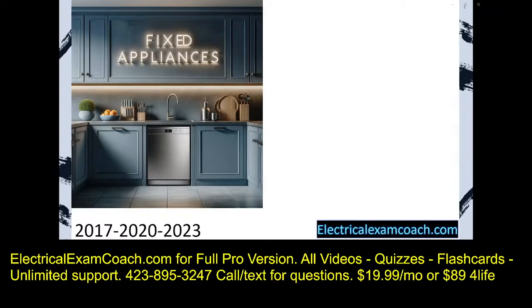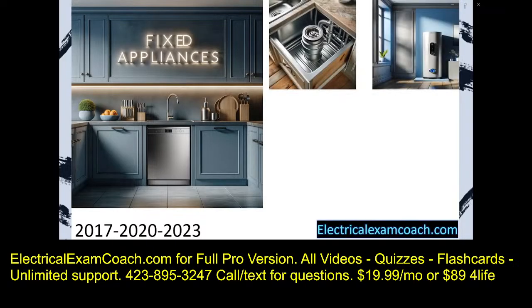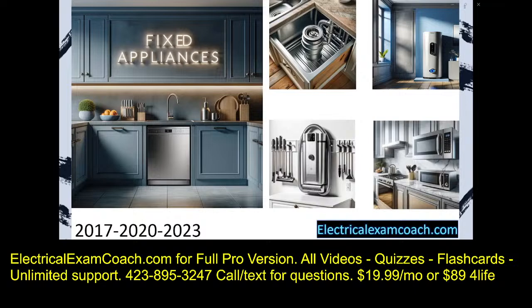Today we're going to be learning about fixed appliances and how they work into a whole house load calculation. Fixed appliances include things like dishwashers in this picture, but it also includes things like garbage disposals, water heaters, central vacuum systems, and microwaves, and pretty much any other appliance once it's fixed. You'll notice in this bottom right-hand picture that there's 2 microwaves. One is not fixed, and the other one is fixed. And when you fix it to the wall or fix it so it can't move, either with plumbing or mechanical vents or anything else, it now becomes a fixed appliance, and there's a special way that they calculate them when doing a whole home load calculation.